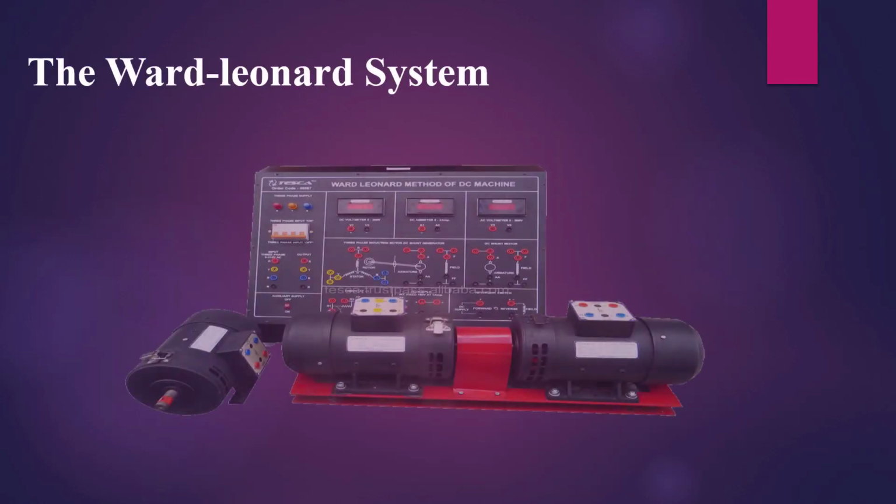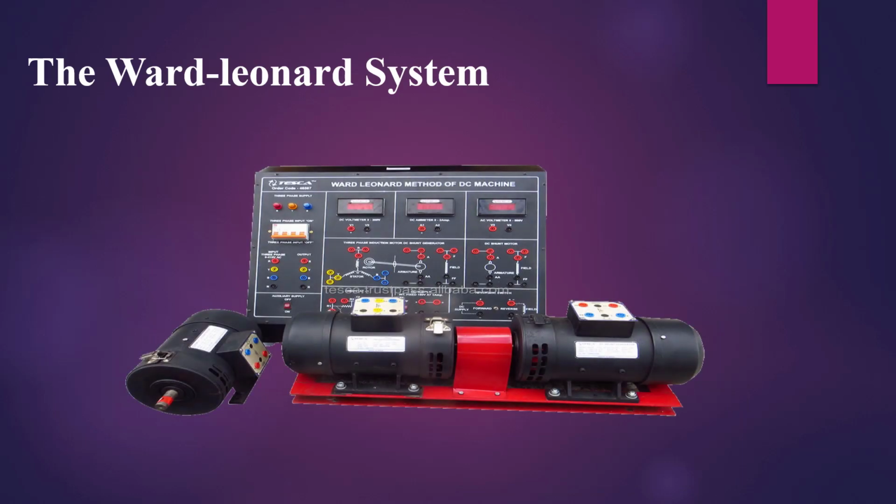The Ward-Leonard system comprises a fixed-speed three-phase AC induction motor driving a separately excited DC generator that, in turn, feeds a variable voltage to a shunt-wound DC motor. So, this is essentially a DC variable speed drive, a complex structure that has largely been replaced by electronic devices.